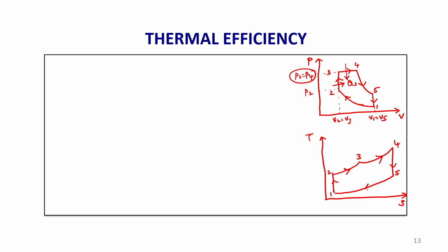So, this is 5, okay. During process 2 to 3 and 3 to 4, QS is the amount of heat added, and here volume equal to constant, here pressure equal to constant, here volume again is equal to constant, and during the process 5 to 1 QR is the amount of heat rejected. So, during 2 to 3 and 3 to 4 heat is added and 5 to 1 heat is removed. So, the arrow mark should be pointed towards the right side. Okay, it should be away from the system, not into the system. Heat is removed from the system. So, this is the maximum temperature.